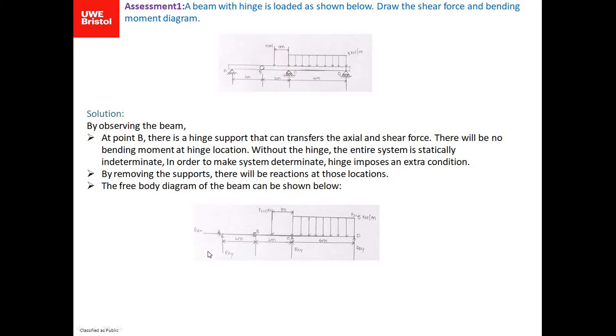Now in order to determine these forces, we need a free body diagram as well as simple calculations regarding concurrent forces, considering that the sum of the forces in the x direction and the sum of the forces in the y direction should be equal to zero. Those equations will help us a lot in finding the reactions at the particular supports, and we can find the shear forces once we determine the reaction forces at the supports.